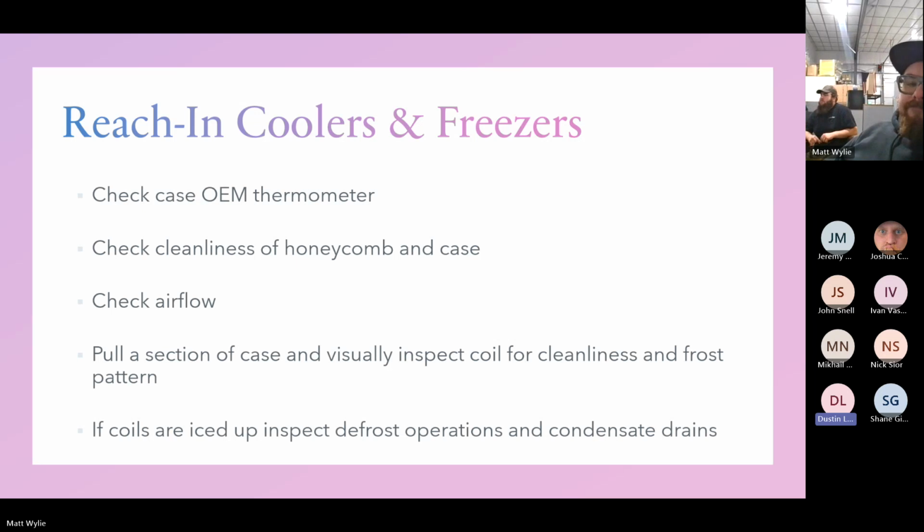It's what's your superheat, what's your feeding pattern, and what's your airflow like? Are there boxes stacked up all the way to the top restricting it? Are your fan blades super dirty? It's not always just a simple, oh, my heaters are working, I'm good to go. And also, if you are de-icing it, you've got to get all the ice out.